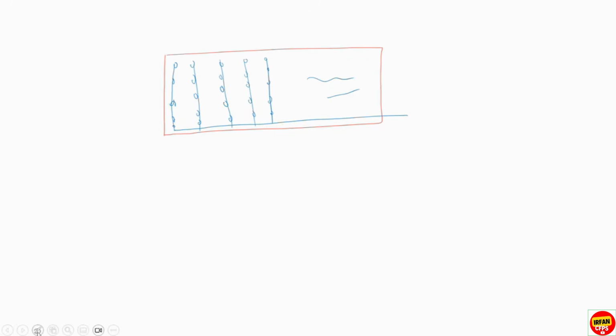Now the S is 10 feet, L is 13 feet. Previously we considered the same, S is 10 feet, L is 13 feet. But previously what we did was consider this as half L from the wall, and this sprinkler as half S from the wall.